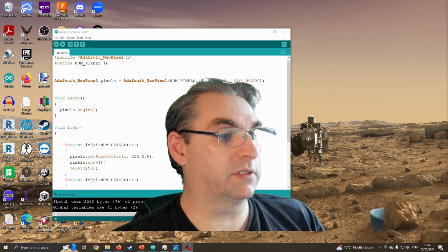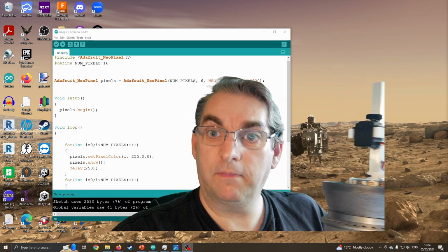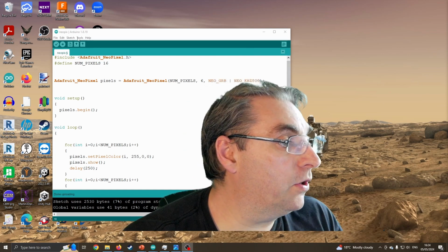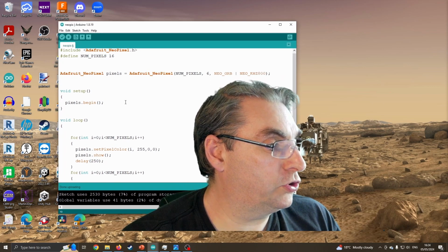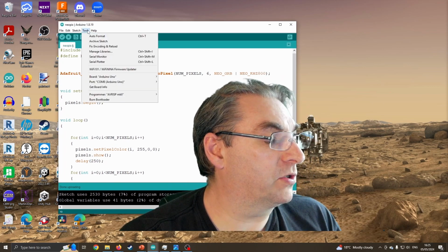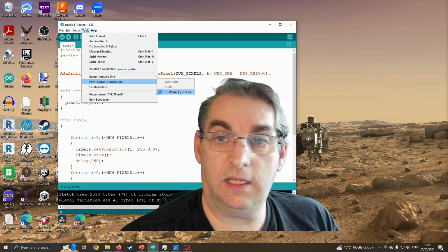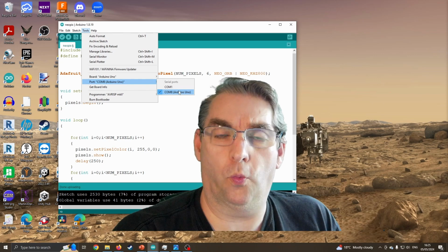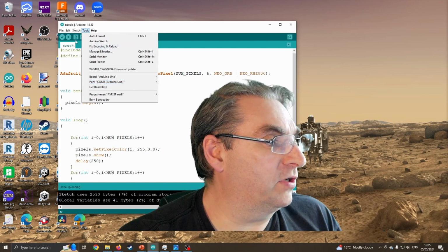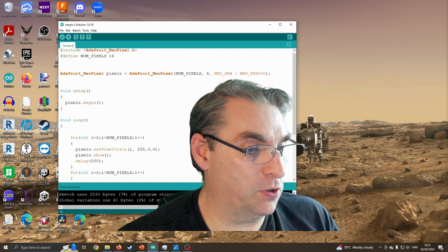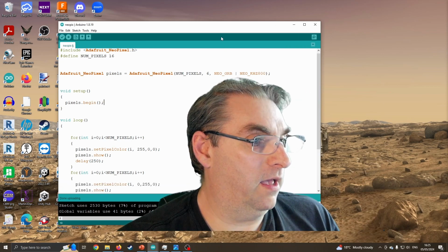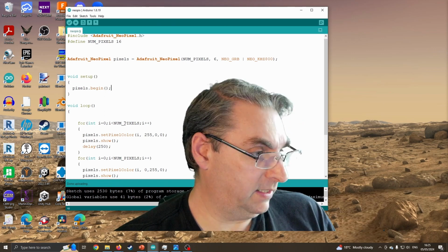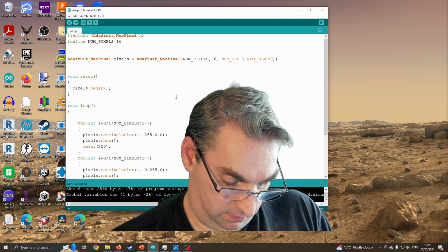So now I've got it plugged in, I think. Okay, so I've now plugged it all in. I'm going to come over to this code and check everything's fine. Going into tools, COM8, yep, that's ticked. Again, it's always a good idea to make sure. I've seen some people, including myself, get frustrated when it doesn't work because we've not actually plugged it in, or it's not on the right port. So now let's see if this code goes across. I probably should have changed those delays, but it'll do for the moment. So it's compiling.